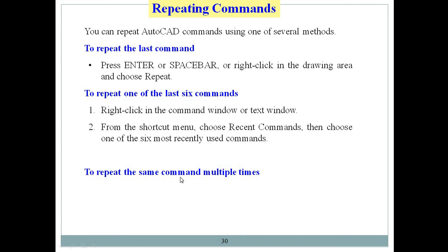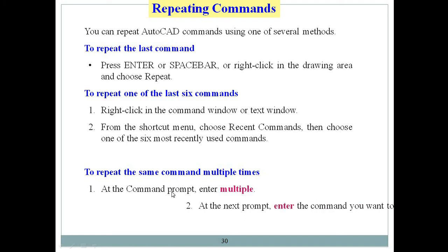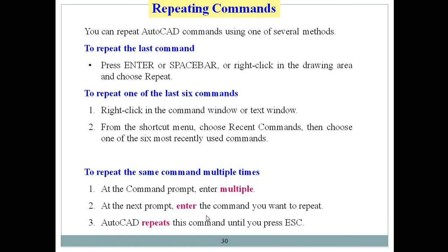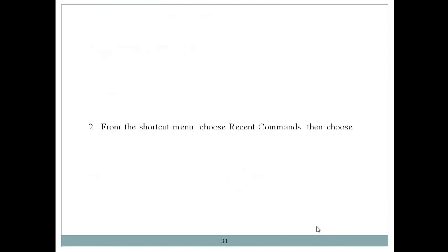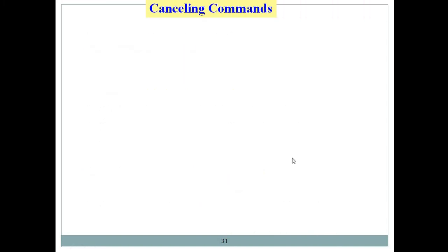Then to repeat the same command multiple times, we have to enter multiple at the command prompt. Then at the next command prompt enter the command you want to repeat. And finally AutoCAD repeats this command until you press escape. Finally close the command.